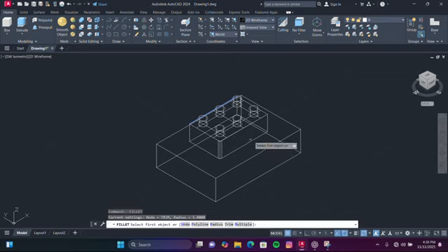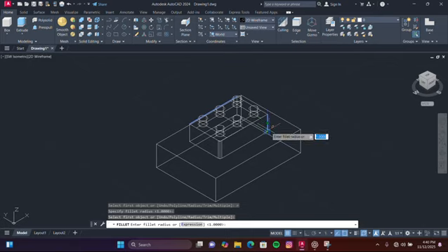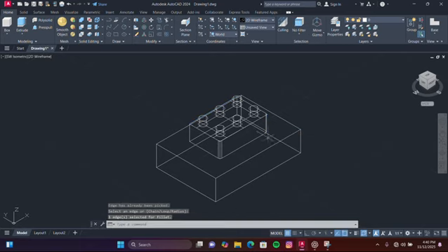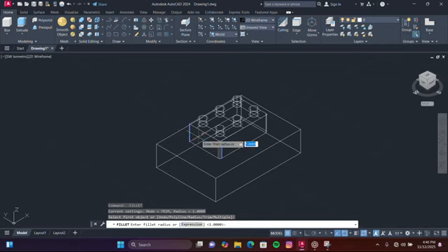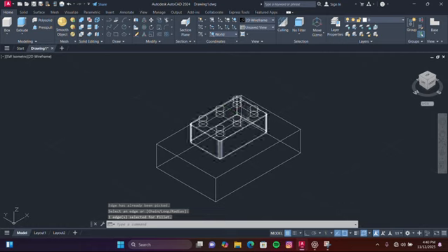Spacebar again, you left click on this and then R, enter, then the distance is 1, then enter, select this line and then enter again. The same thing with the spacebar to repeat the previous command: the vertical line, left click on it. Since 1 is already showing, enter. You now select this vertical line again and then enter. The same thing applies here.